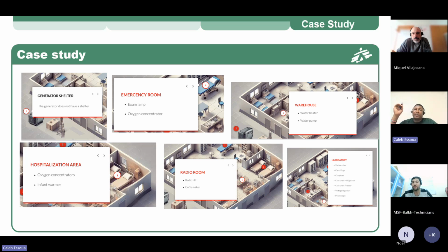This is based on your load. The full load current that you have is what you design the system for. Your main panels should be based on this plus the percentage buffer that you will have.